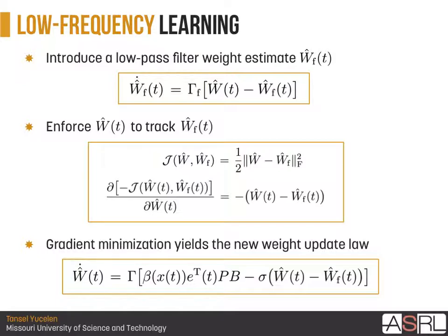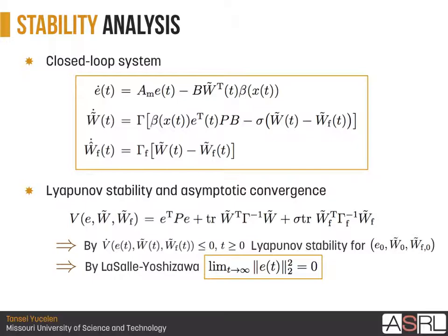So it turns your adaptation into a lag process. And that's why, if you choose sigma to be large, as we discussed this morning, your uniform ultimate bound gets larger and larger. So here, I don't want to drive weights to 0. I want to drive weights to their low-pass filtered version, such that I will obtain a smooth and nice and fast adaptation.